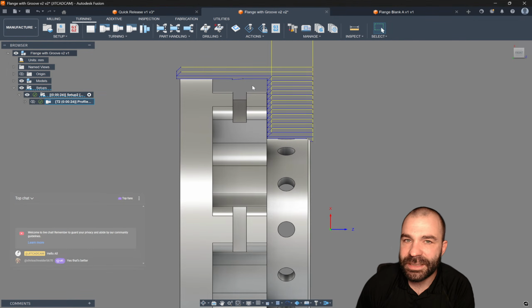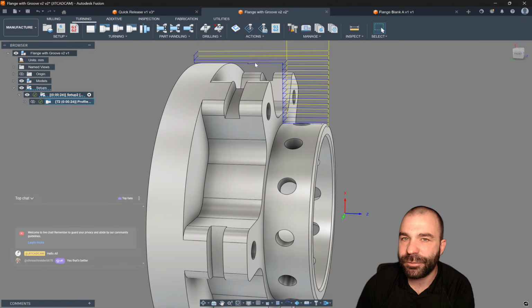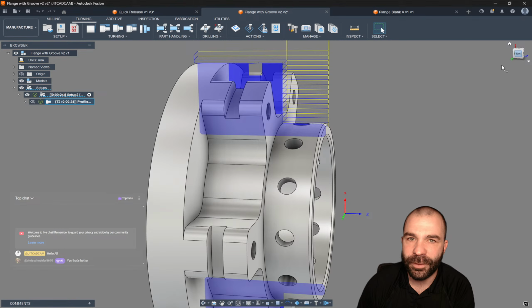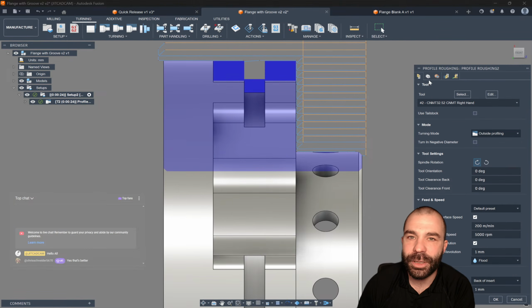In the case of this part, you're going to notice that my tool path, again, is waterfalling because of where that groove is. This is why we have settings like show spun profile. And now you'll see, when it spins this kind of cog, we do have a groove there, which again is why we're falling into that groove. So again, we go through and adjust our tool path.